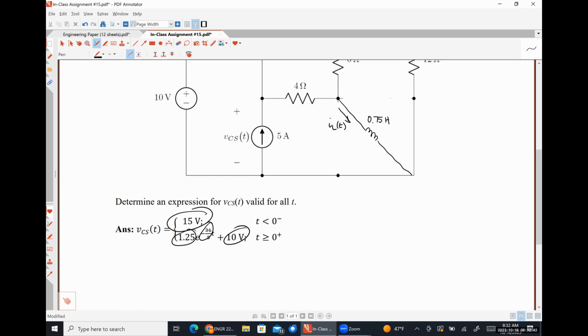This cable right here is your function generator leads. It has a BNC connector on one side, and a pair of alligator clips on the other side. This is what connects your function generator to your circuit. This is how you're applying your time varying signal to your circuit of interest.